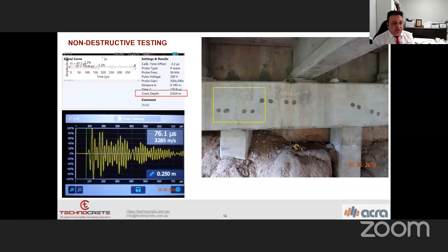Both of them. For the non-destructive testing, we have to use high quality equipment. Those equipment should be calibrated regularly. And yes, the number of tests is important, because for each experimental testing in field or in the laboratory, we have to do the statistical analysis in order to find out the errors involved and the statistical deviation of the numbers. We have to gain as many test results as we can. The higher the numbers, the more accurate the outcome.